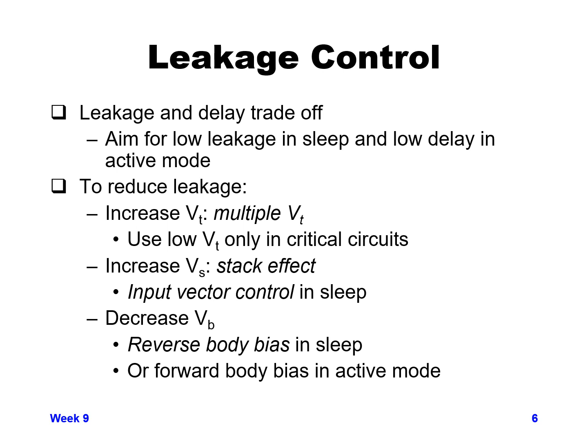In either case, trying to monkey around with your body bias voltage is a lot more difficult than some of these other effects, and so it's probably done less often. But if you have the right circuitry and the right expertise to do it, it is a mechanism to try and reduce your leakage.